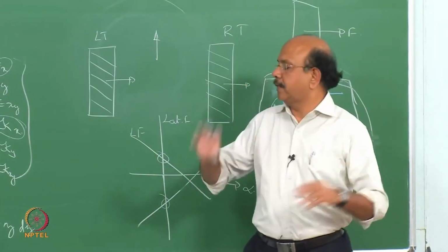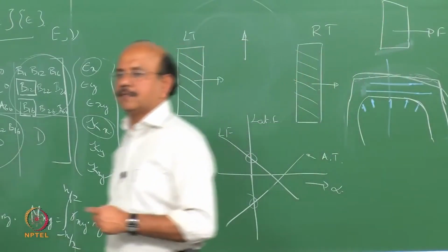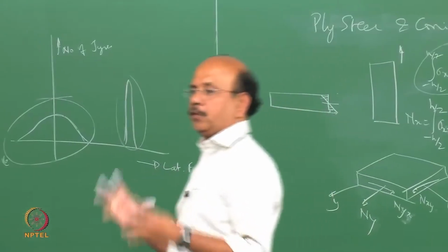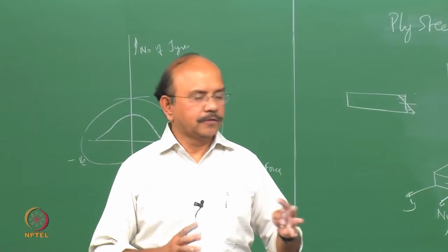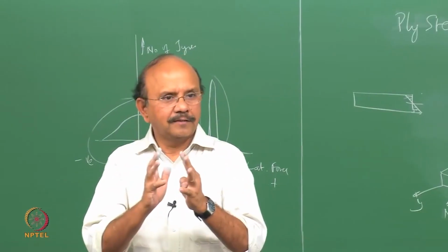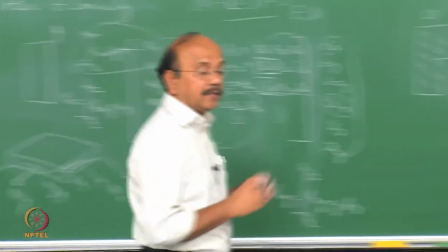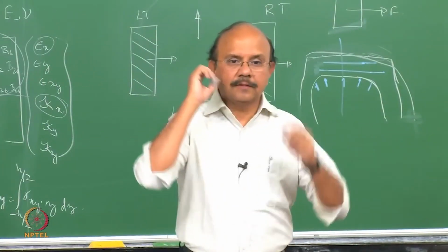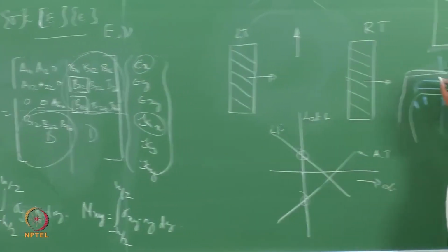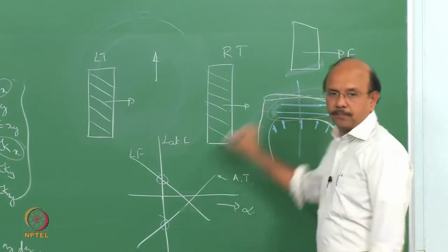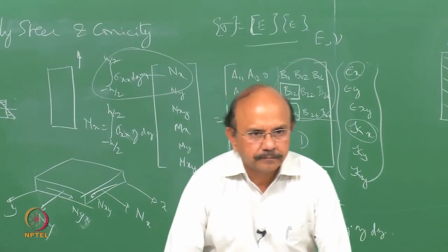Let's look at whether there are any other things that cause a peculiar behavior of the tire. In other words, is a straight running tire going to be a nice guy who runs straight, or is he going to do other magic? Is the conicity a manufacturing defect, or something else? Yes, it is. In most instances, it is this belt offset that causes conicity. It's a defect.